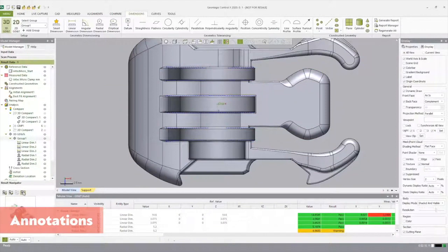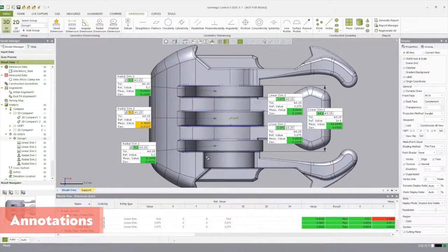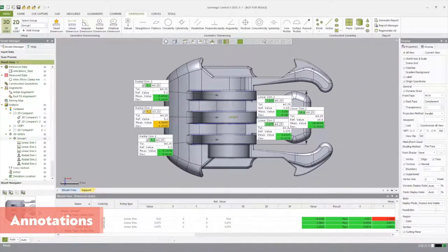For more individual dimensions, left mouse button click on a specific dimension type. Use the same as Smart Selection. For reporting purposes, orient the part in a way that best depicts critical information. Highlight 3D GD&T in the Model Manager, and in the Result Navigator hit the Reassign Viewpoint, and this will now be generated in the final report.